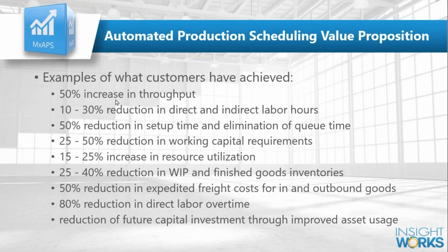Well, the problem is now the one they were supposed to work on is delayed, and that delays the downstream processes. And what happens is you end up generating a ton of WIP and everything is late. So if you walk into a facility and you see a ton of WIP out on the shop floor, but everybody's busy and production orders are coming in late, you've got a problem with scheduling, specifically local optimization, most likely.